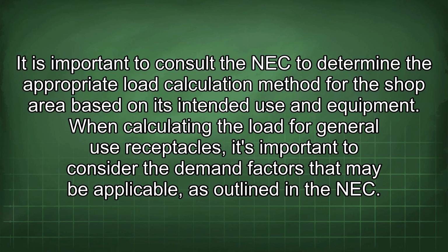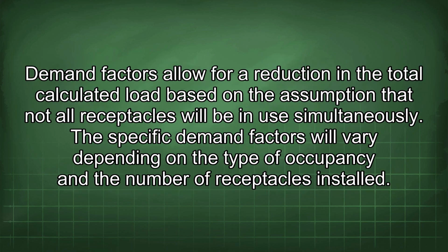When calculating the load for general use receptacles, it's important to consider the demand factors that may be applicable as outlined in the NEC. Demand factors allow for a reduction in the total calculated load based on the assumption that not all receptacles will be in use simultaneously. The specific demand factors will vary depending on the type of occupancy and the number of receptacles installed.